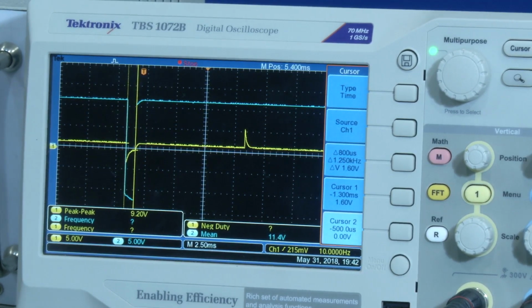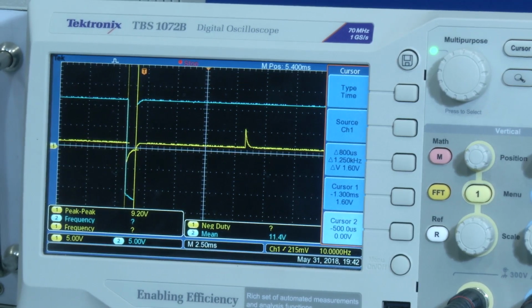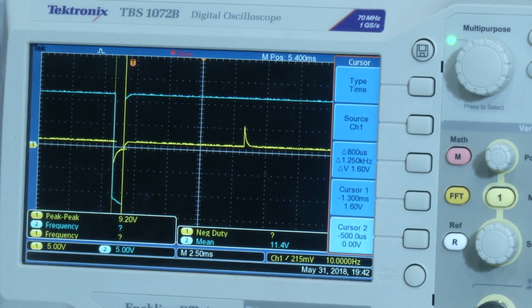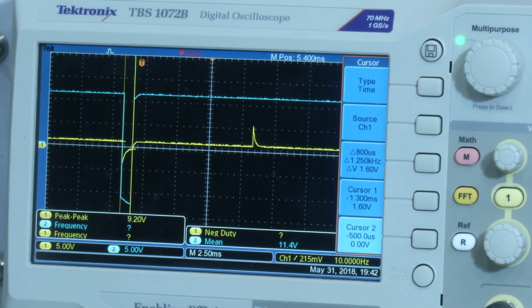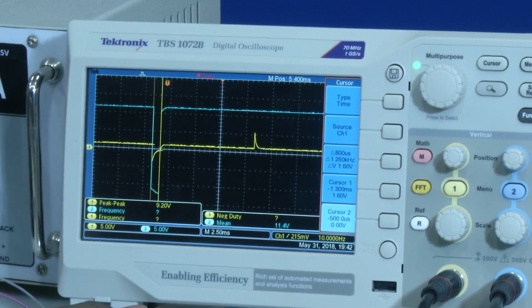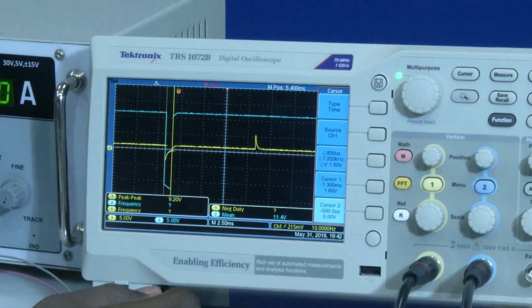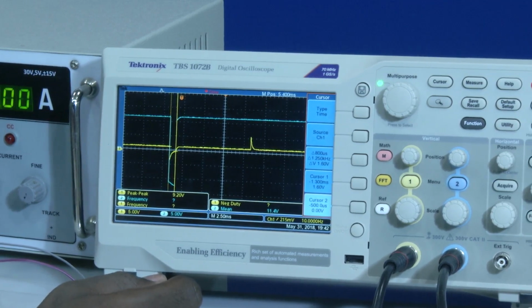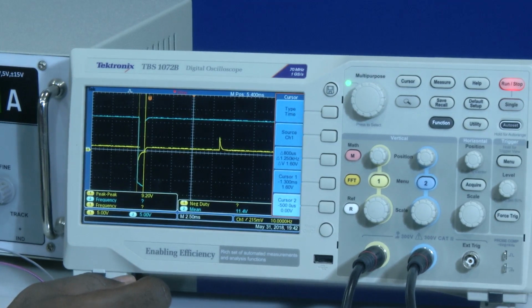So, that means we can understand that until we generate a triggering pulse for a monostable multivibrator, we cannot see any change in our output because of our diode, which makes the capacitor stay at 0.7 volts, which will not allow the capacitor to charge more than that. Since it cannot charge, the voltage at VA, which is nothing but the negative terminal, is smaller than the higher threshold value. As a result, the output will always stay at plus VCC, right.